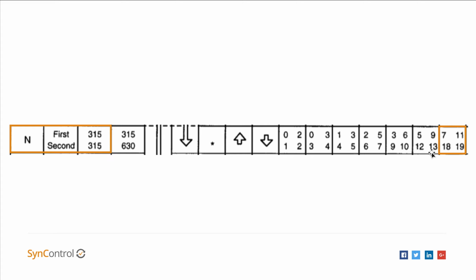And there's a case, 8, 9 or 10 defects, where you need to pick another 315 samples, and then the limits, now you add up all the number of defects from the first and the second sampling that you did, and if it's 18 or less, it's accepted. If it's 19 or more, it's rejected. And then at that point, you've picked 630 samples, and you can make a decision with a higher confidence.